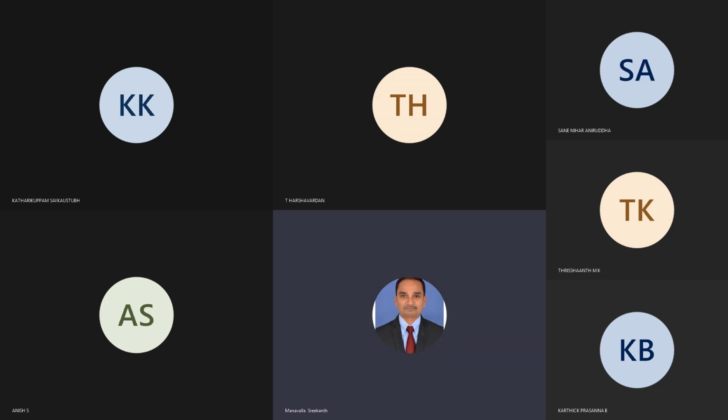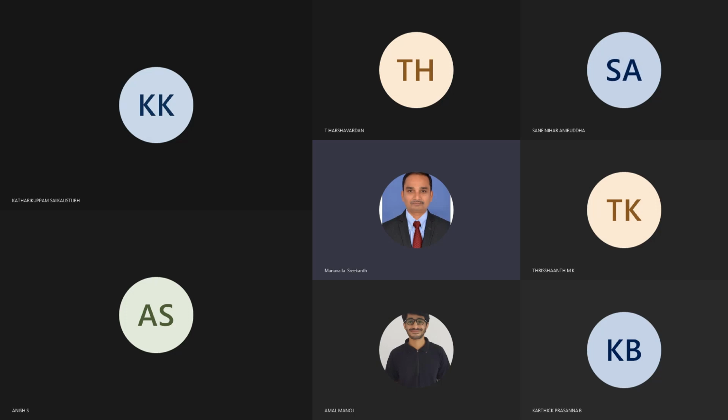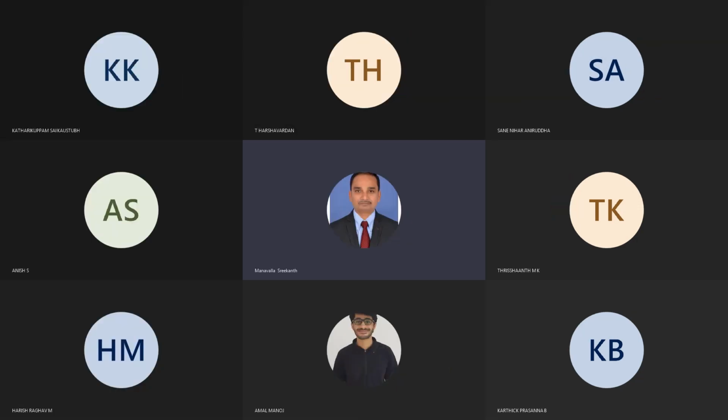The second method is having a limited application. That method is called the graphical method, or the method of using the flux plot. That method is suitable for systems where the boundary conditions are a combination of constant temperature or adiabatic boundary conditions. So when the boundary conditions are one of these two or a combination of these two, we can attempt a graphical solution. That means if there is a radiation boundary condition or a convective heat transfer boundary condition or a constant heat flux boundary condition, we cannot use it.